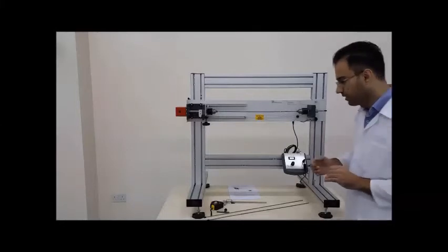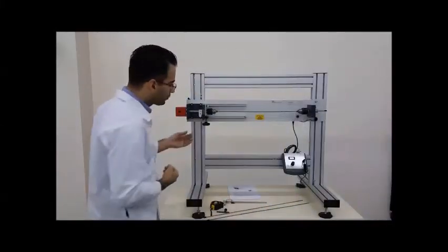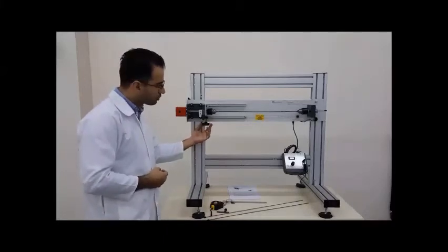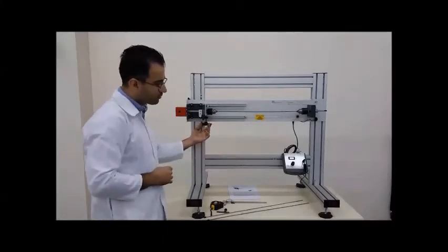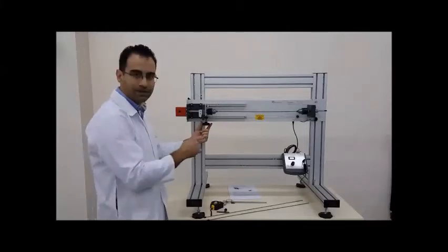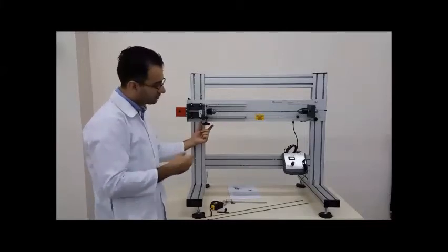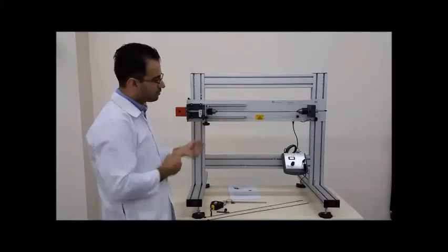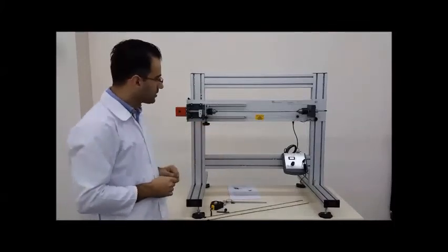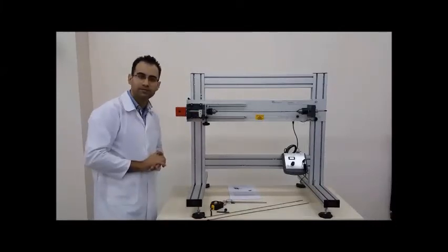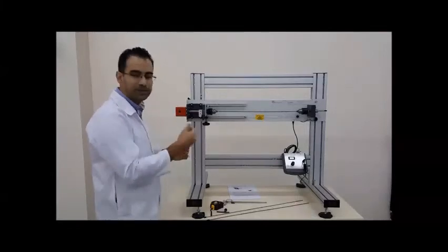Right, so you start at 0. So if you're at 0, your angle of twist should be 0, right? That would be the first part of the data sheet that you might have filled out if you were doing the test. And now you start increasing the torque using that knob that he's turning now. Then you turn it up to 1 Newton. So you apply 1 Newton of force, and you do it very slowly till you get up to 1 Newton. And then you're going to read the angle of twist. And that angle is actually read in degrees, I believe.